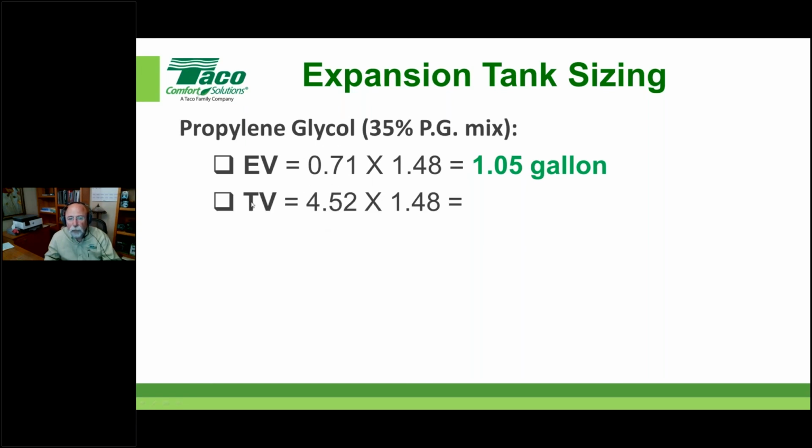And I do the same thing with my tank volume. Watch what happens there. 4.52 times that same multiplier, I'm going to see 6.7 gallon tank required. Okay, that's just to show you that when you start mixing glycol together, your tank's going to get bigger. That's a rule that you can walk away with and understand. Okay, understand that association. Glycol is going to expand more than water. I'm going to need a bigger expansion tank.